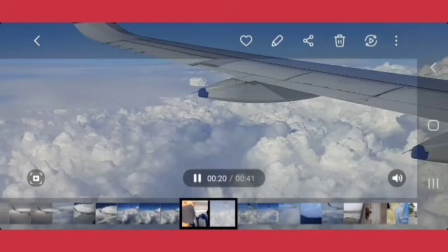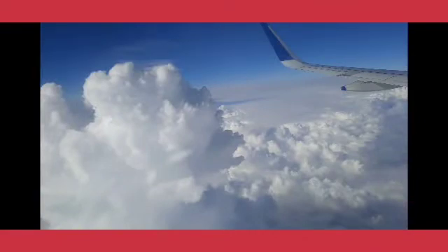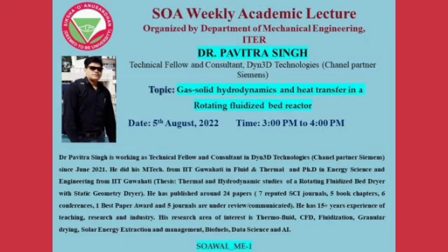So this is the formulation used in this calculation. So we can calculate the tangential average radial gas velocity by using the formula UR is equal to Fg upon 2 pi R L epsilon G, where Fg is the total gas flow rate, L is the length of the reactor, and the length of the reactor is this one.